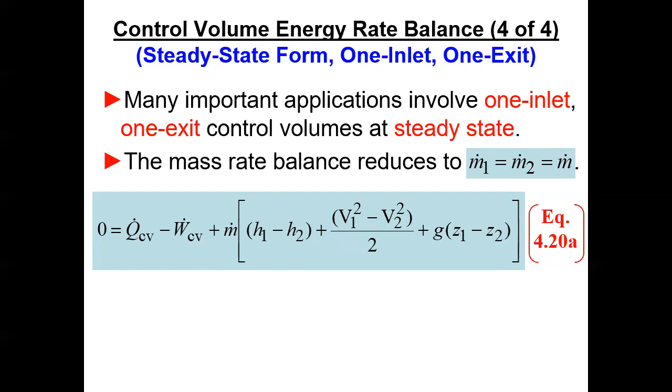Okay? So that's like what, megajoules or kilojoules or, whatever you want, BTUs. Work is the same thing. I mean, they have to all produce the same units or you can't add them together, right, in the same equation. Inside the big brackets, what? Enthalpy is going to be what? Kilojoules per kilogram. See, all of this stuff is per unit mass inside the bracket, but I multiply it by the mass flow rate, which then clears the mass units from all bracket terms.